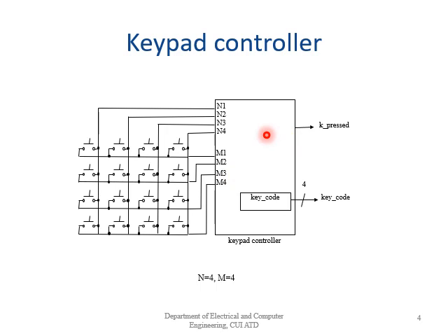So after 100 milliseconds it can check whether the key is pressed and what the code is, and read the register, that is the key code, when the key pressed pin is high. Or the output can generate an interrupt, eliminating the need of polling. So this key press can generate the interrupt, and at that time we can read the key code register.